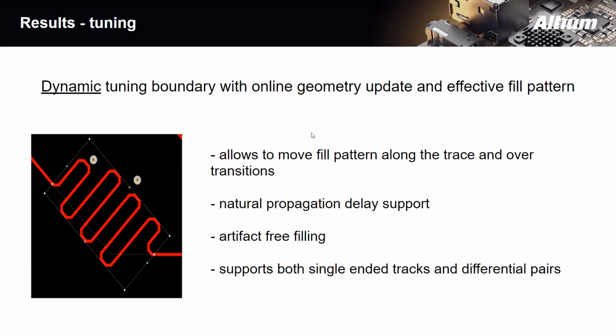And the third one, related to tuning, is probably the most unique feature in the whole PCB EDA suite world, because now we have a completely dynamic boundary for tuning filling. It means you can move this boundary across the whole trace, change direction, and the filling geometry will be updated online. It's not shrunk by nearby obstacles.